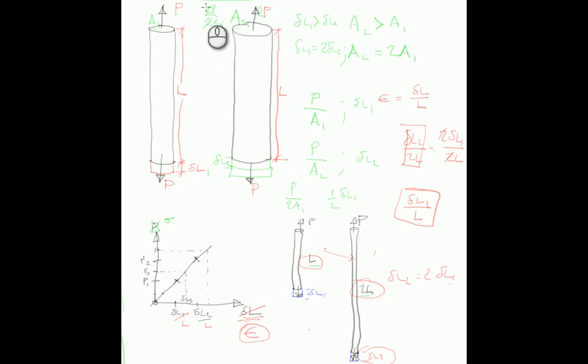this quantity, this property of this sample here, back in line, such that we can plot stress on this line against strain and then have a line which is relevant to all samples regardless of their cross-sectional area and regardless of their original length.